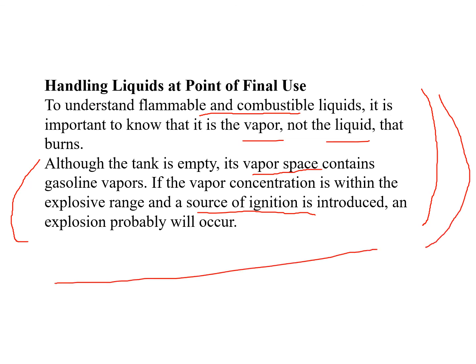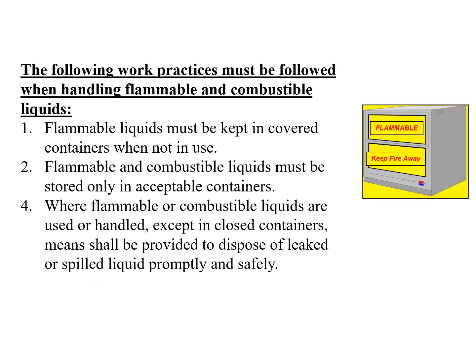If we are using any cans, whether we keep them in the car, for example, or in the kitchen, or sometimes in the labs, we think it is finished, that these are empty cans. But since the vapors of the combustible or flammable liquids are still there, if an ignition source is introduced, it will cause an explosion, if the vapors are within the flammable limit.